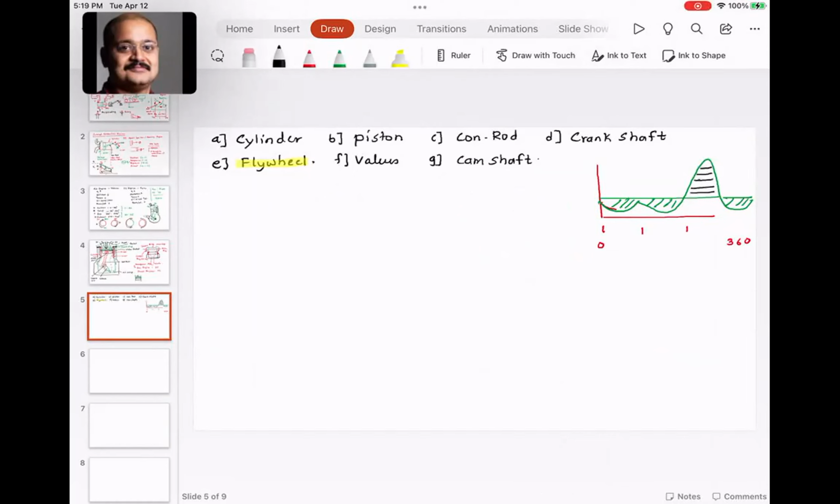The chemical energy in the fuel gets converted to mechanical work. So unfortunately, if we continue to run the engine like this, there would be a power spike during one cycle, and then there will be a significant drop during other cycles. So what we do is, to the side of the engine, so this is the engine, and I'm going to show you a stationary engine, you have a big inertia wheel. This is called the flywheel.